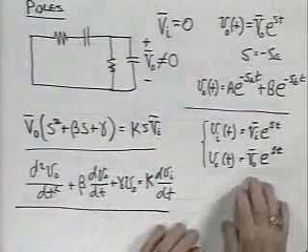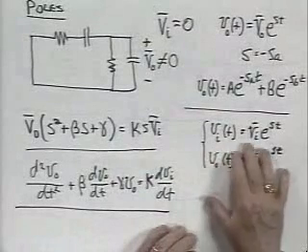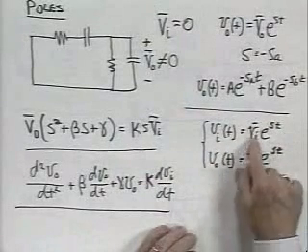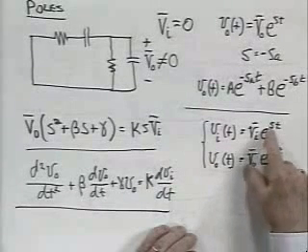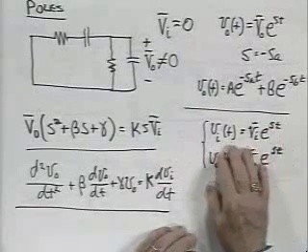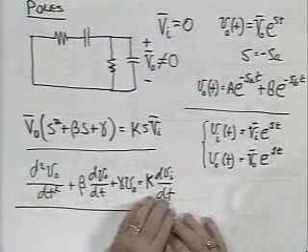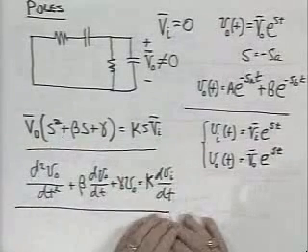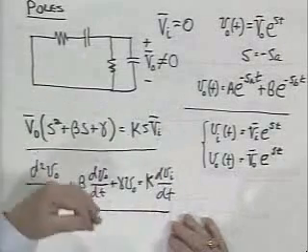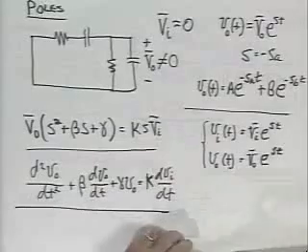If we wish to, for some reason, get back to the differential equation, which is, I suppose, the most fundamental way of describing the behavior of these circuits or systems, you do it by looking at the transfer function multiplied out in this form, recognizing that the time functions are defined in terms of the complex amplitudes, and the natural frequencies, represented here by S, are defined in this manner, which means that this differential equation must produce that relationship among complex amplitudes. So having only this relationship, I can go backward term by term to build up the differential equation.